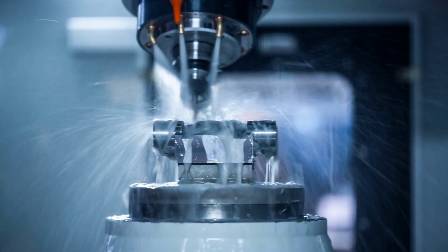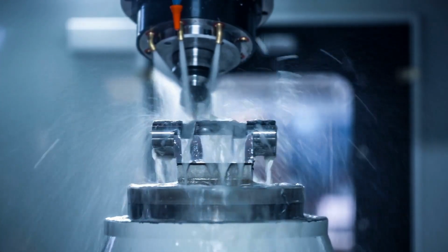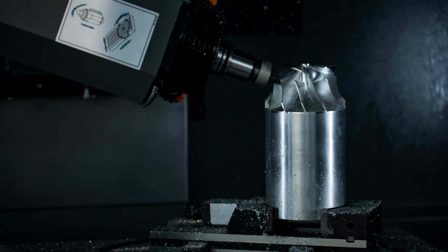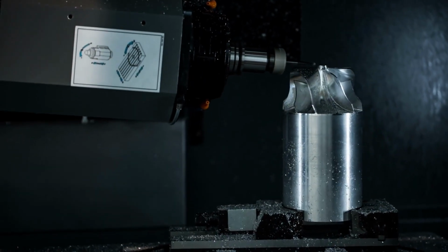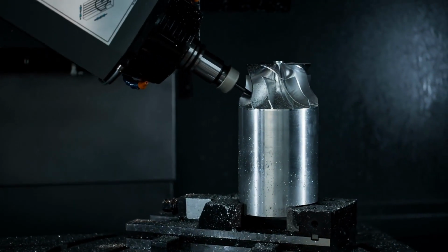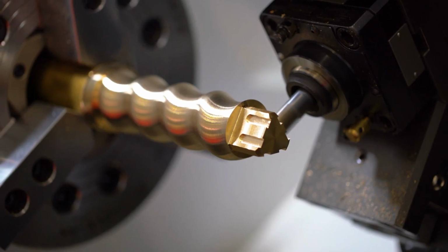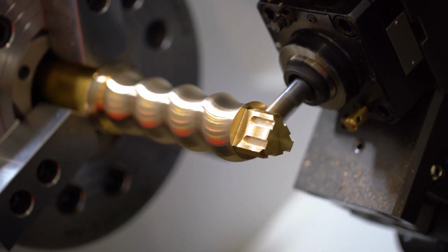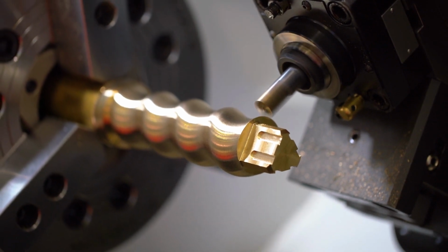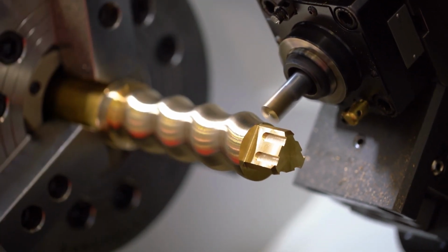For example, increasing the X coordinate value moves the table left, but looking from the perspective of the tool, it's moving right along a workpiece. Increasing the Z-axis coordinate would move the spindle up, decreasing it would move it down into a workpiece. You are cutting into the piece, which corresponds to a negative Z-axis coordinate. If reading that left you more confused than before, don't worry.